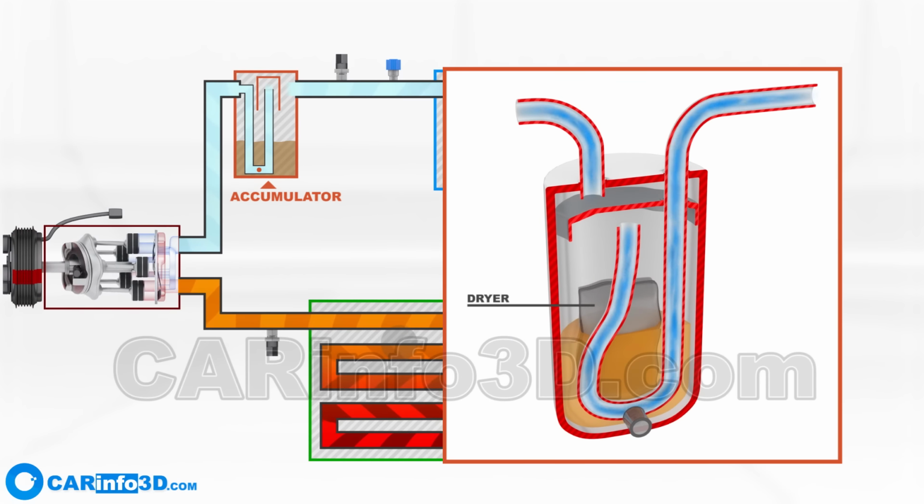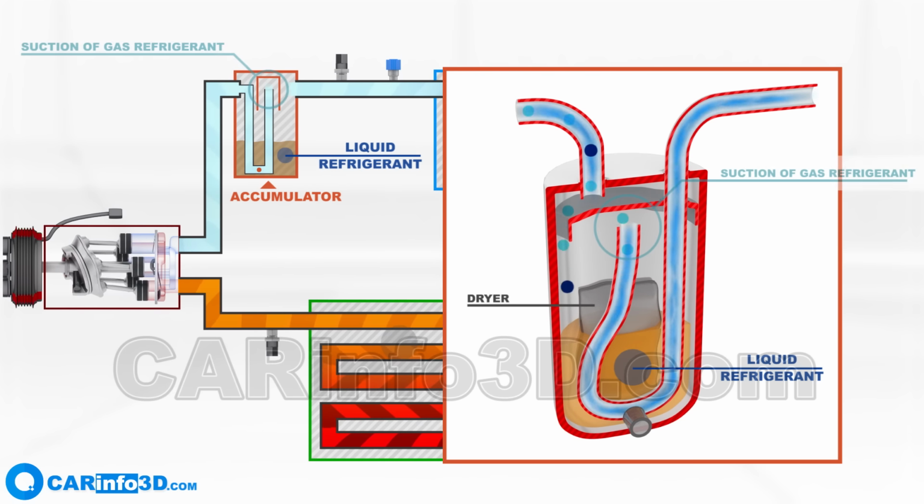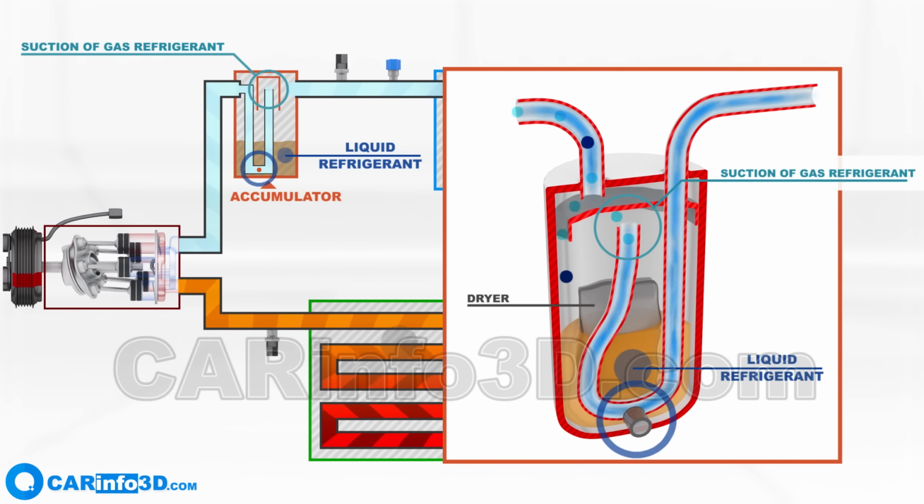The liquid refrigerant settles in the lower half of the accumulator tank, while the gaseous refrigerant from the upper part enters the compressor. The lowest part of the suction tube has a small hole to catch compressor oil as it settles to the bottom.